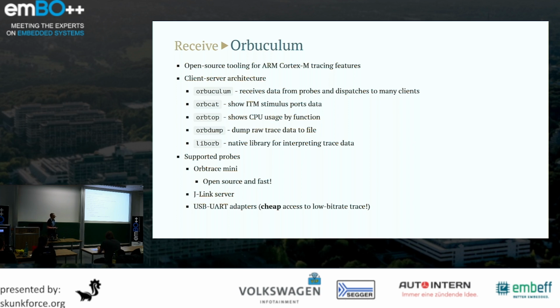It's based on a client-server architecture with the Orbuculum process that is responsible for talking to the hardware probe and receiving the trace data. And it outputs that data to a series of clients connected via TCP sockets. So you can plug anything into that process.